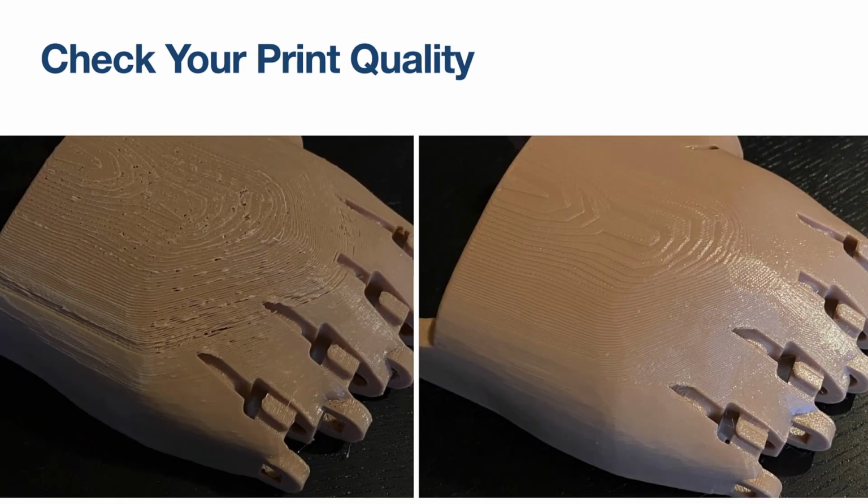And here's just an example of one print that I had done a while back. On the left, you see it done with a spool of material that had taken on some moisture, and you can see obvious quality issues there. And over on the right, you see what a proper quality filament results in. A nice clean print, great surface finish.